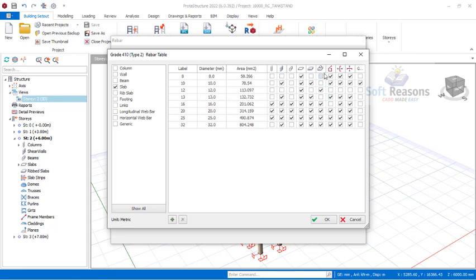After which go back to the slab right there. What we have here, we remove 8, we remove 10, we have 12, we can remove 13, and we have 16, 20, remove this 2. This is for the reinforced concrete slab. We have this 16 here for the foundations, also 20 for the foundations, just like this. Then for the links, we will be using 8, 10, and 12. So we'll remove the rest of that for the links.